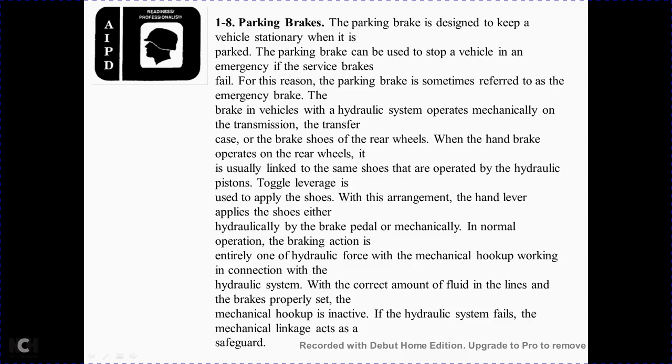1.8 Parking brake. The parking brake is designed to keep the vehicle stationary when it is parked. The parking brake can also be used in an emergency if the service brake fails, and is sometimes referred to as the emergency brake. In a vehicle with a hydraulic system, the parking brake operates mechanically, through the transmission, to apply the brake shoes at the rear wheels.